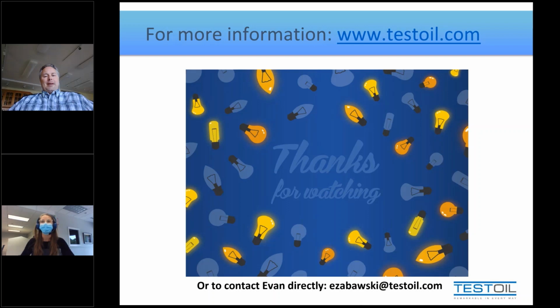And then we also have someone asking if you can give some advice when they want to sample from a refrigerant compressor. Probably that question is coming from somebody who's wondering about the gas entrainment that occurs. When you're sampling that, it's quite likely you get a lot of excessive foam. So two things. One is you might want to use a larger sample container so that you're not worried about having too little sample once the foam all settles. But the other part of it, usually people wonder about the gas.